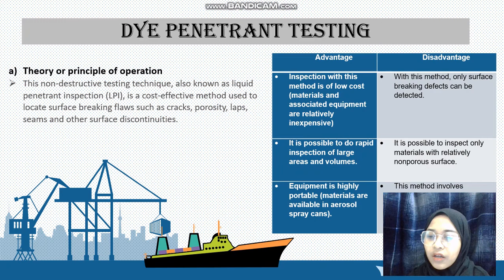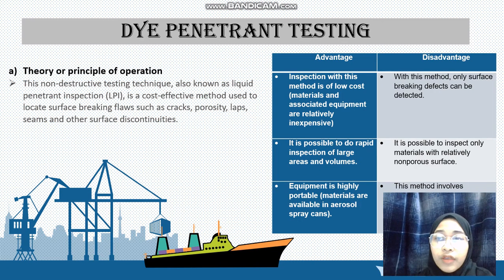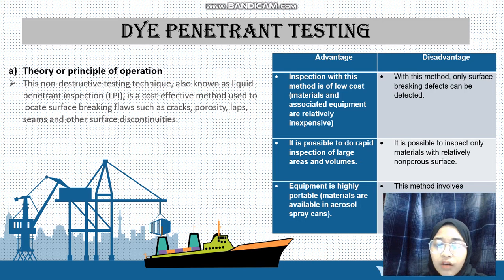The limitation of dye penetration testing is that with this method, only surface breaking defects can be detected. It is possible to inspect only materials with relatively non-porous surface. And finally, the disadvantage of dye penetration testing is that these methods involve chemical handling and its proper disposal.